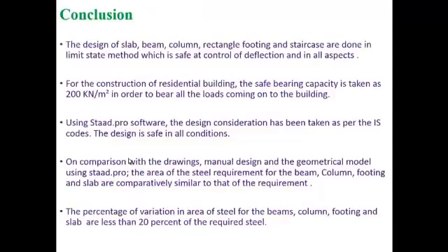Conclusion: the design of slab, beam, column, rectangular footing and staircase are done in the limit state method, which is safe with control of deflections in all aspects. Using Staad Pro, the design consideration has been taken as IS codes. The design is safe in all conditions. The percentage of variation in area of steel for the beam, column, footing and slabs is less than 20% of the required steel.